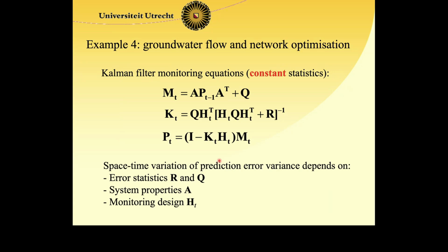And the nice thing about the Kalman filter is that if you assume that your system dynamics are not changing in time, which is usually the case if you have a strictly linear groundwater problem, that is, if you are looking at groundwater flow in confined aquifers, then the system dynamics are not changing in time.